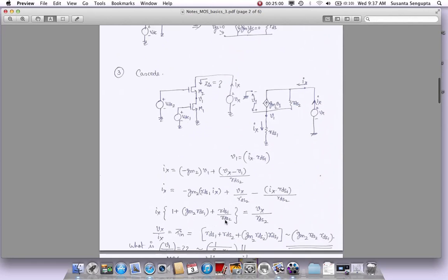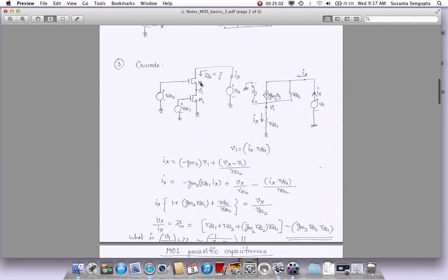Okay, so in this example what we did is we solved for output impedance, and we found that it's boosted significantly by the gain of this intermediate stage that we put in, and it also helps as a shock absorber to attenuate whatever the voltage swing here is. It gets divided down by the time we come to this point here.